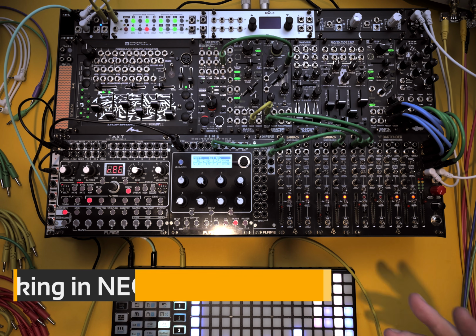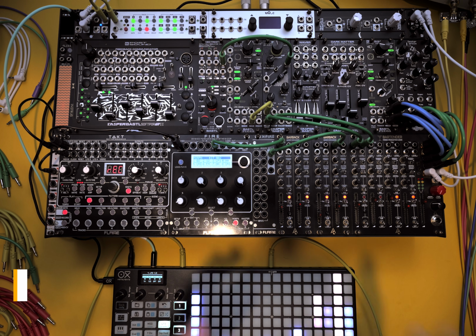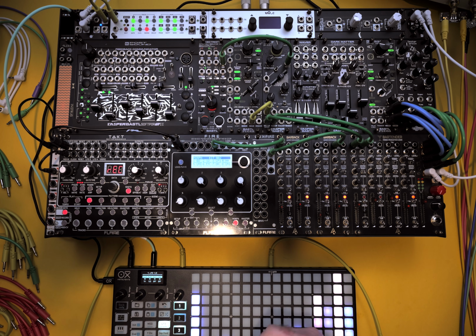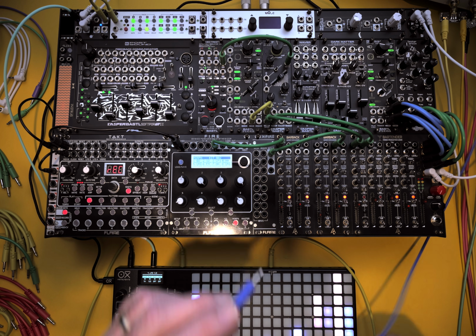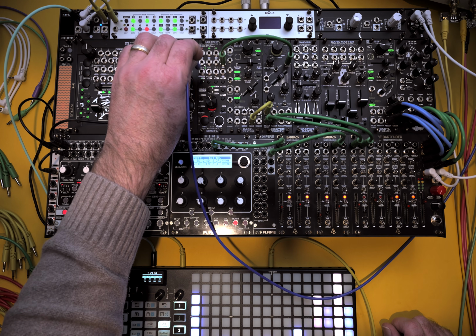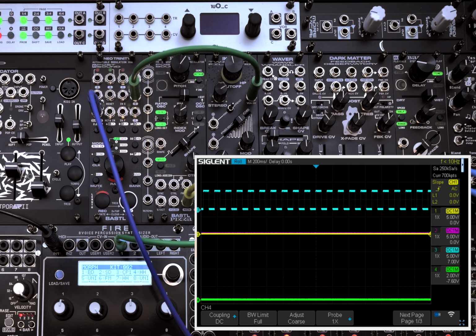Well, I've been talking about clocking and clocked and unclocked LFOs. So let's explore how the clocking works in Trinity, because understanding this actually opens up some very interesting patching ideas. We'll first start with just looking at the internal clock and how you can adjust the clock rate. So I'm just going to patch the blue channel here on my oscilloscope, which is channel 3, to clock out, and we can see our clock is running, the internal clock is running.